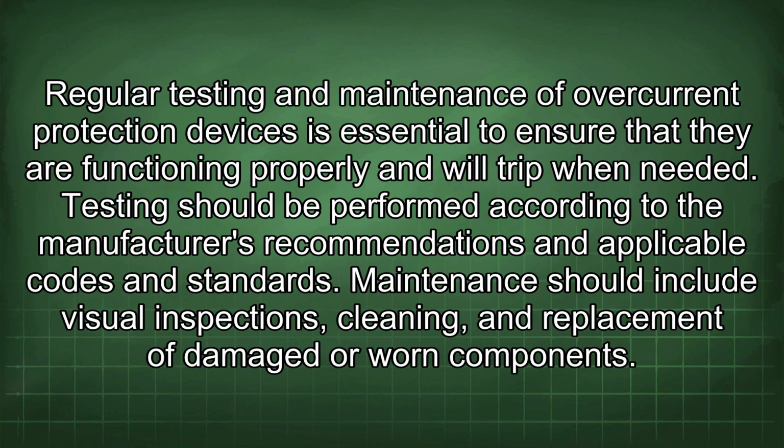Regular testing and maintenance of overcurrent protection devices is essential to ensure that they are functioning properly and will trip when needed. Testing should be performed according to the manufacturer's recommendations and applicable codes and standards. Maintenance should include visual inspections, cleaning, and replacement of damaged or worn components.